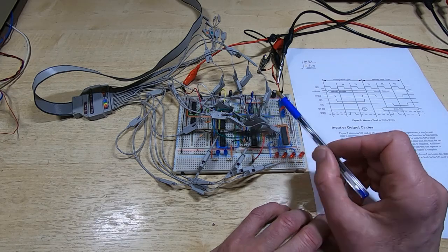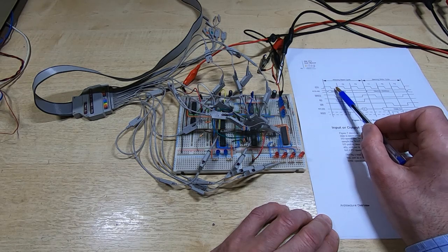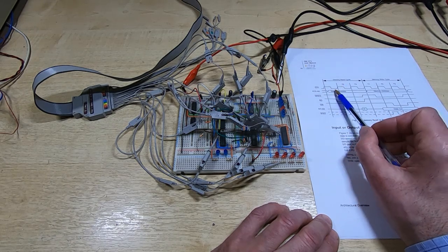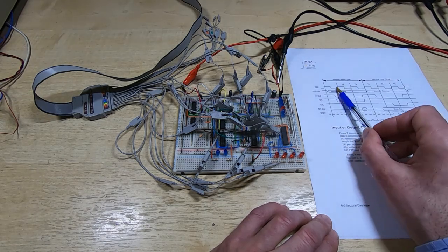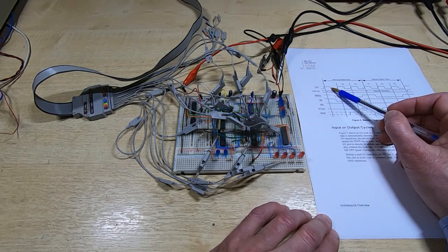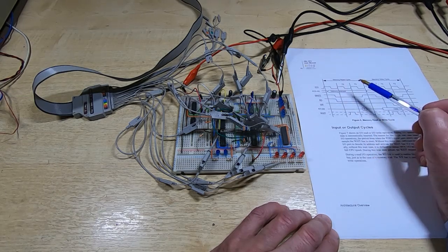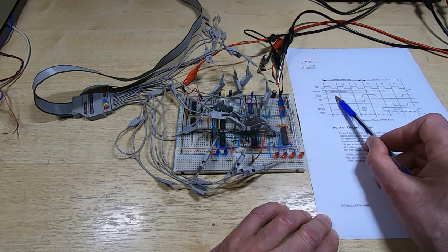and I've used a flip-flop with complementary outputs. So for each phase we have both a high going signal and a low going signal, and that's exactly what we need to be able to make use of the clock phases. All we have to do then is for each output from the 4 flip-flops, we use those to control the relative timing.